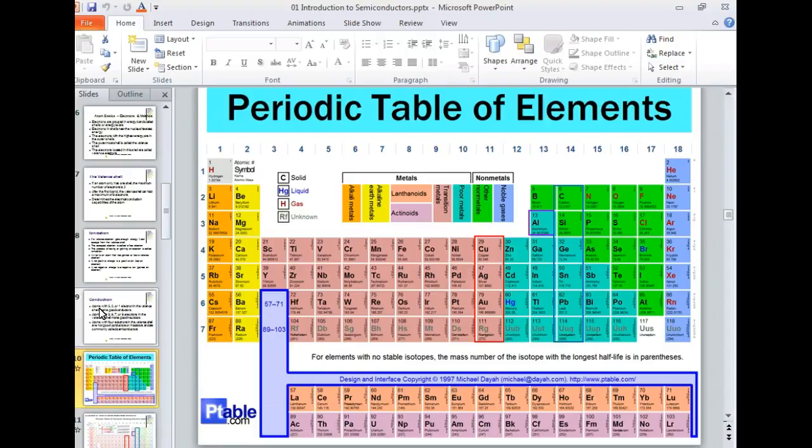Another thing we have problems with is, y'all ever heard of dissimilar metals? Mixed dissimilar metals. When you put 2 dissimilar metals together, it sets up what we call electrolysis, which makes them corrode a lot faster, and they'll sit there and eat themselves up. Copper and aluminum are dissimilar metals. So we cannot directly mix copper and aluminum.